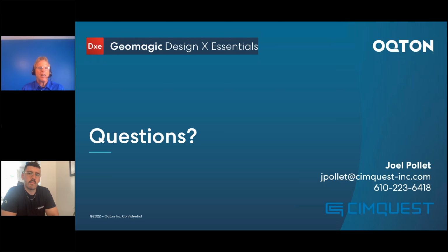If you were using a modeler like SpaceClaim or Creo or something that has direct modeling capabilities, direct model editing capabilities, then something like Design X Essentials would still probably work fine because those products can import Step and Parasolid and make edits to them. So that's the major difference, though, is exporting a history tree in Design X versus exporting Step or Parasolid in Geomagic Design X Essentials.